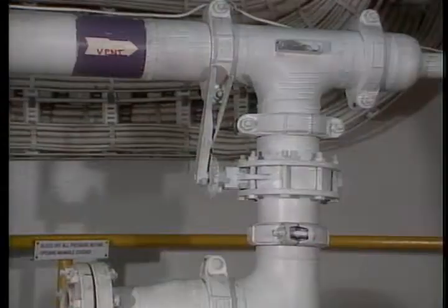When the tank is fluffed, all that you're really doing is unpacking the contents. They'll tend to settle and pack in because of the rig vibrations. When it's fluffed, it will generally distribute the bulk more evenly inside the tank. This will give you a more accurate measurement of the level of the tank.